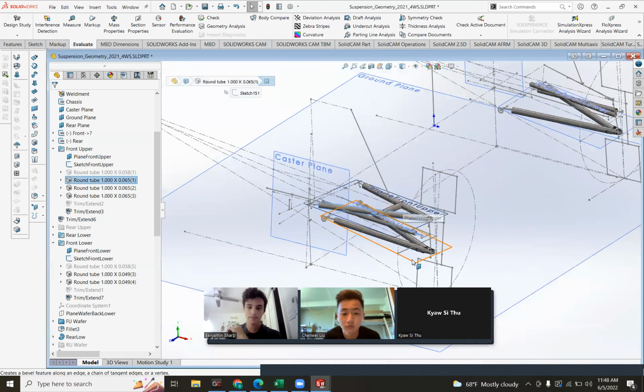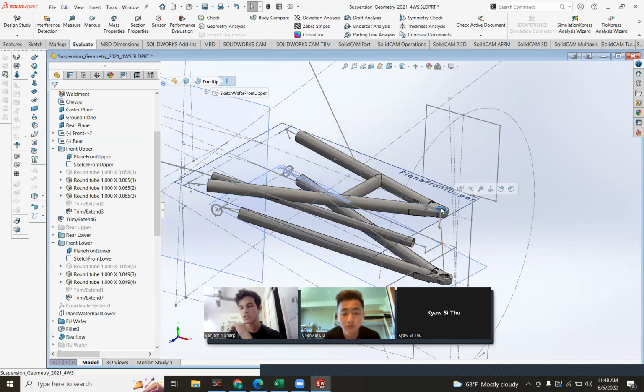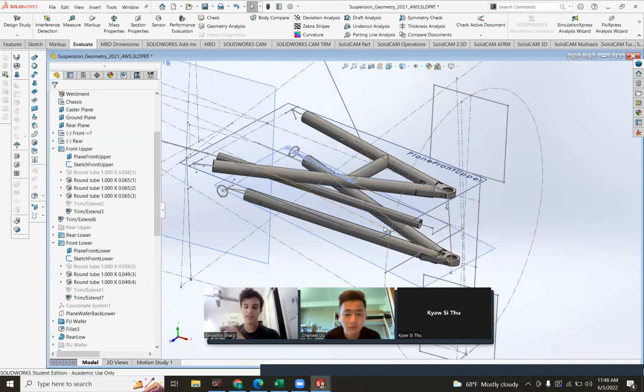When there's a front impact, the front of the tire gets hit. It's going to push this spherical bearing back. It's going to push this spherical bearing back. And that is the load case that you should use for the non-load bearing arm, because in that case, it is going to see some stress and some bending. But if the non-load bearing arm, so if the bottom A arm is wide, you can make it really thin, because that means the geometry is set up well so that it can take that front impact, right? We talked about that. And because the geometry is set up better, the thickness can be lower.